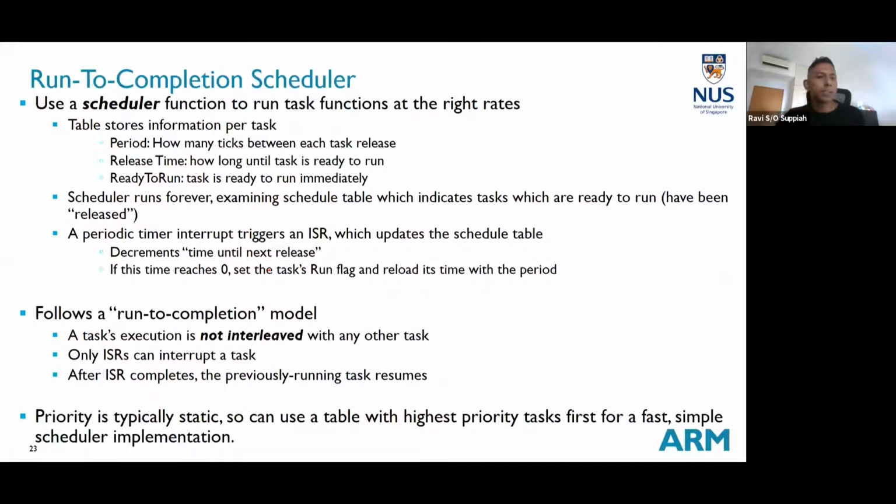For the run to completion scheduler, if you want to implement it on your own, you can create a sort of lookup table, where you store some information on, for example, the periodic interval at which I run a task, when is the time I need to release the task, and what is the state of the task, and so on.